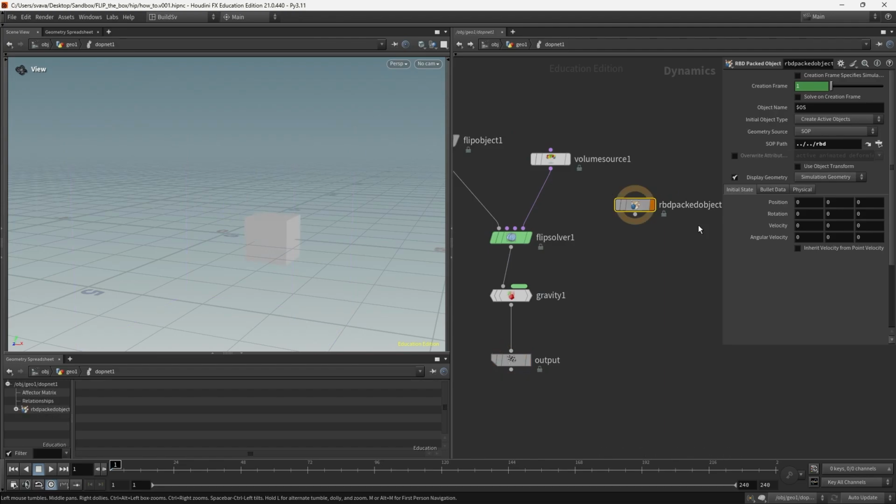And we got it. You can change the density of the box. So now it's 1000 kilogram per cubic meter, which is the same as the density of water. And theoretically, for things to float in water, their density needs to be lower than the density of water. So I'm just going to take it to something low. Let's start with 10. So it's a very light box.